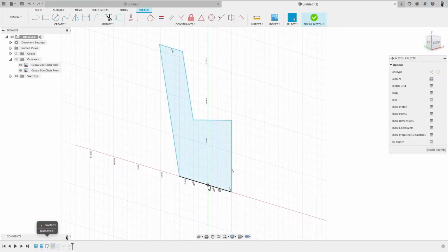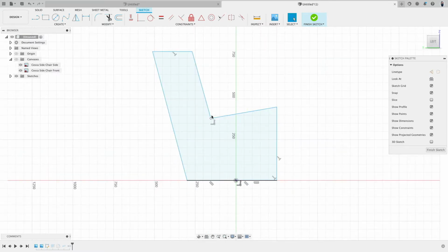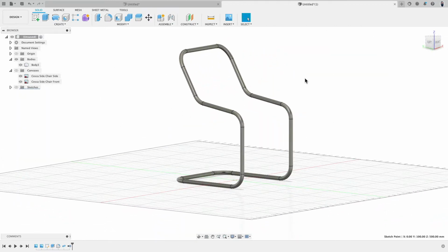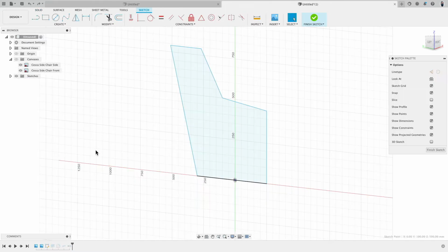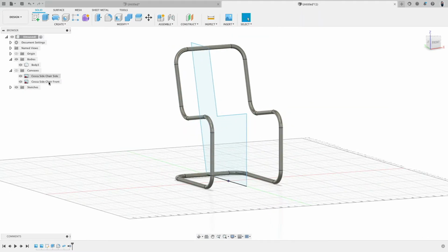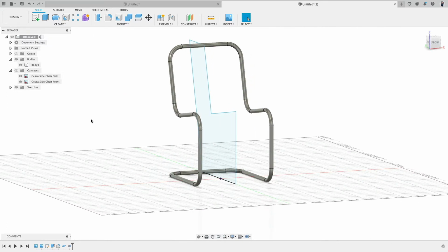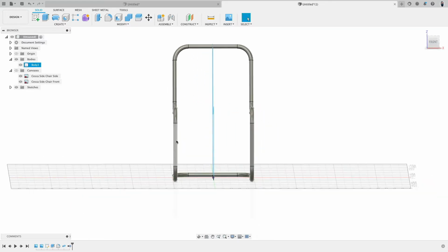Because this is all in the timeline, when we go back and then manipulate something, say we don't want someone to really sit on this chair, then we change the input geometry or the sketch. That changes the extrusion, that changes the edges, and blah, blah, blah. Easy, pretty cool. So let's undo this step. Very good. But what I find too boring is how here everything is just straight up. Maybe I would like the sides to angle a little bit. So to angle the pipe, going maybe at a degree of 2 degrees.